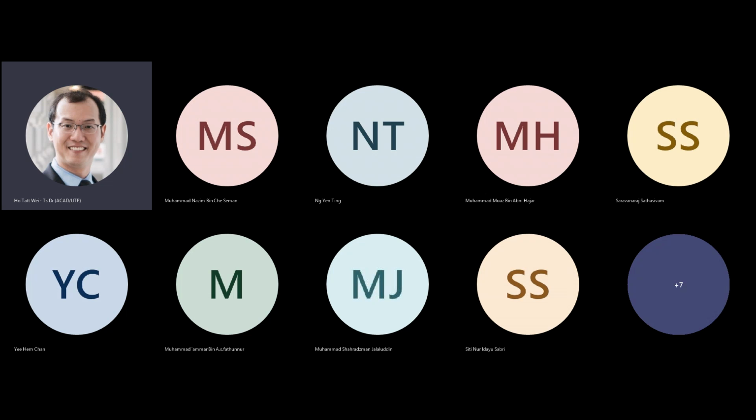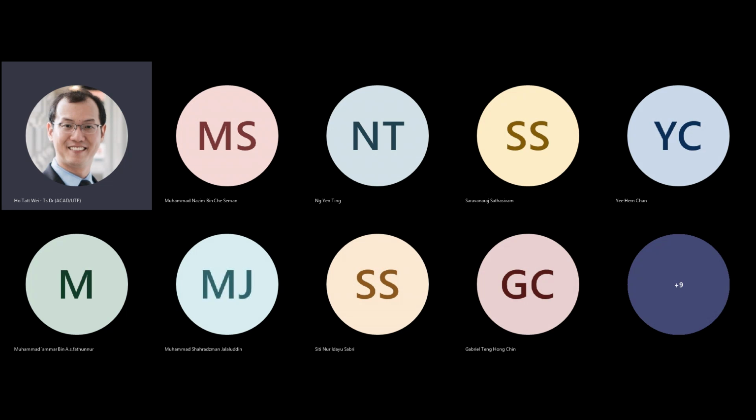These would be the places where they actually make the chips, but they have developed the specific recipe for each of these individual transistors, how they connect, and the timing and energy properties of all these basic gates. There'll be an array of gates of different sizes made available to you, and all those gates are known as a technology library. And in ASIC terms, you call this your standard cells, because they are standard logic cells from which you'll be constructing your gates.